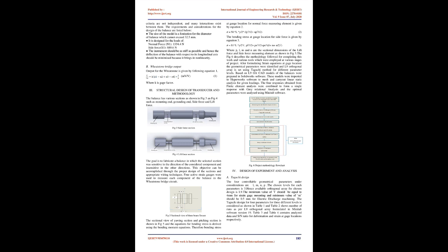The size of the model is a limitation for the diameter of balance, which cannot exceed 32.5 mm. It is designed for the loads of normal force, N1, 1334.4 N. Side force, S1, 889.6 N. The instrument should be as stiff as possible, and hence the deflection of the balance with respect to its longitudinal axis should be minimized because it brings in nonlinearity.